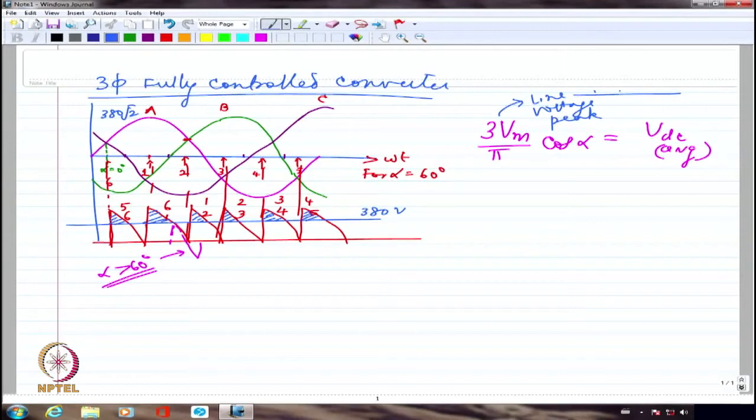People who have done until here, they have calculated whatever is the Vm sin omega t value minus the battery value divided by R, the whole square, and integral of, that is where many people have gone wrong, from what degree to what degree. It will conduct only for 15 degrees. It will not conduct more than that if you actually calculate. So it is starting at 120 and it is going until 135. That is how it will be.